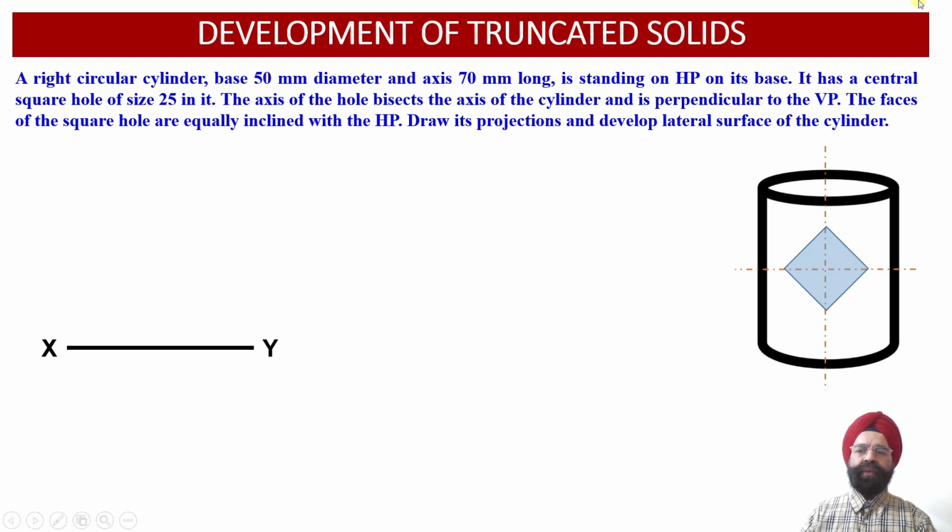As the observer is going to look at this right circular cylinder from the top, we are going to view the circular projections of the cylinder into the top view projections obtained onto the horizontal plane, and these circular projections will be drawn below the XY reference line.